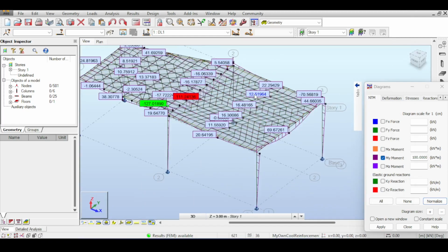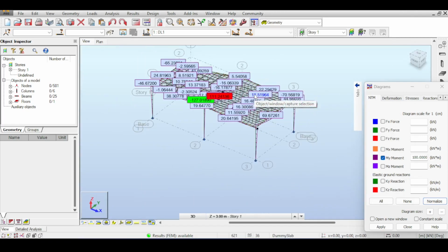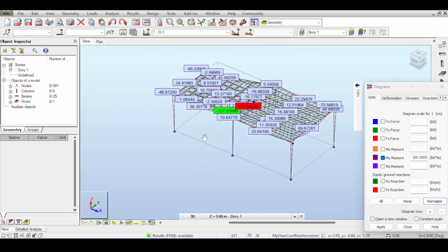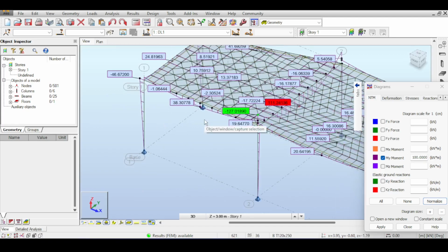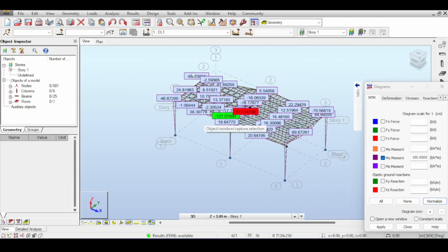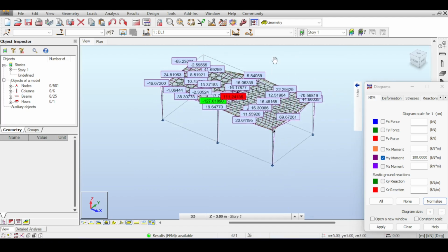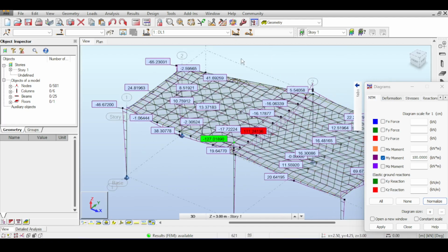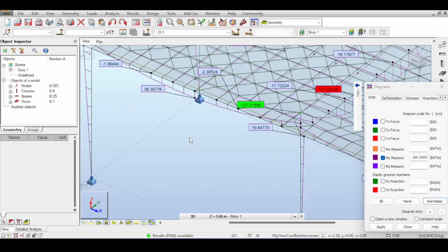I think I've been video recording for 50 minutes, and I don't want to wing it because I want to talk about the design of those ribs in the next video. You need to exercise care because those ribs do not carry any shear stirrups. And we need to find a way in Robot to do that. Otherwise, I would have to tell you that it doesn't work. So I will have to wait for it for the next week. But for now, I think I am happy.